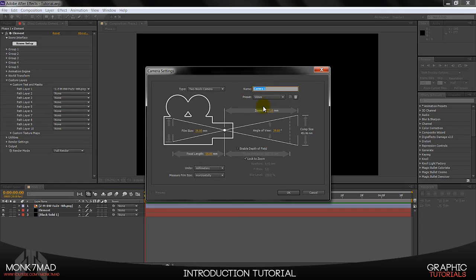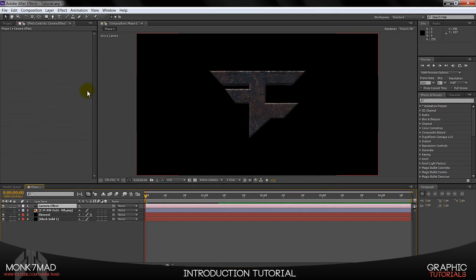You can use multiple cameras to create multiple different keyframes, so your different phases, if you like, or you can just overwrite the same one. It's up to you. I think it's probably better if you do make more than one camera, but it doesn't matter. Then you can just give it a name. I'm going to call it camera effect, and we're going to go OK.